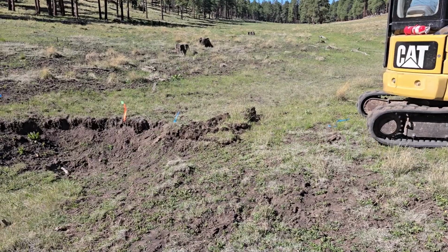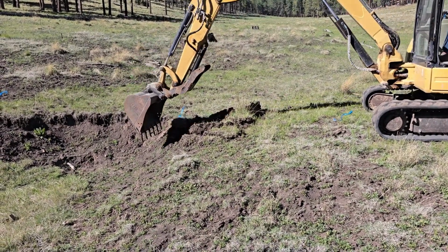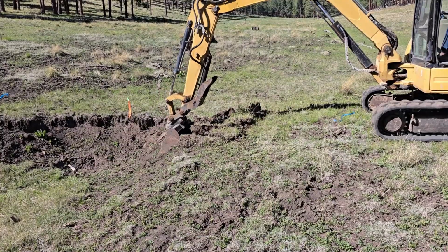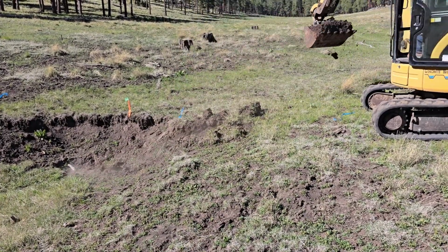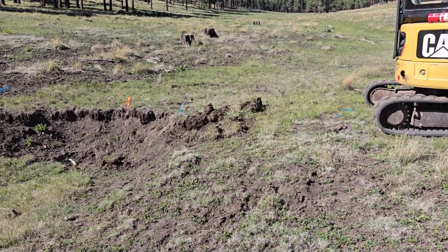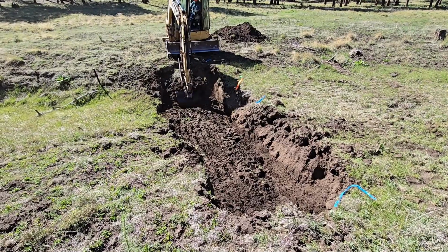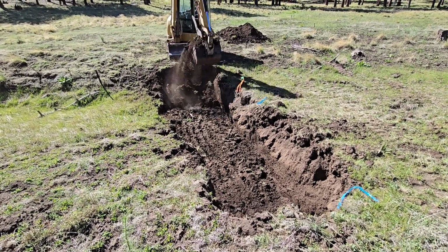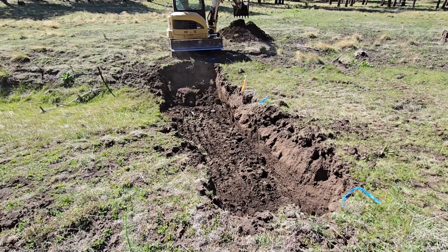The trench was dug to span the width of the 100-year floodplain so that rock could be keyed into the banks and not simply placed on the surface of the ground. He piled the soil that was removed so it could later be used to cover the rock and to shape gradual banks on either side of the trench. The bottom of the trench is dug so its elevation will be the same or lower than the elevation of the top of the nearest buried vertical grade control structure we're building downstream.